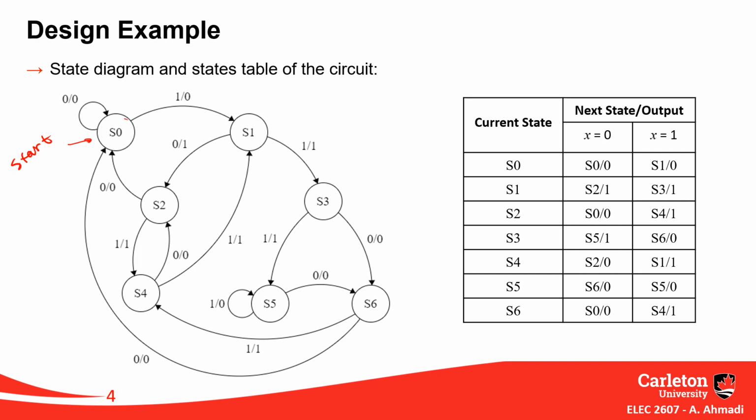At state 1, if you receive 0, you go to state 2. If you receive 1, you go to state 3. So at state 2, for instance, what we have had is probably a number of zeros before. We don't know how many. We don't care how many. We have had 1, then 0. Now look at this pattern. You have 0010, which is number 2, which is a prime number. That's why my output is 1, right? And we are in state 2.